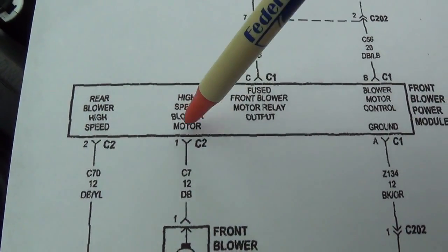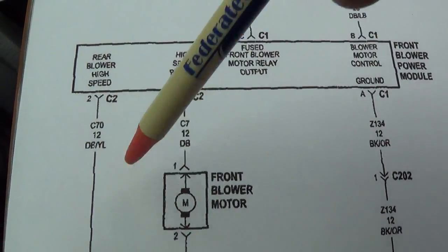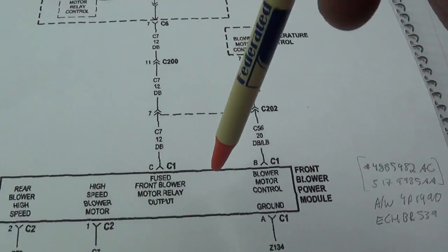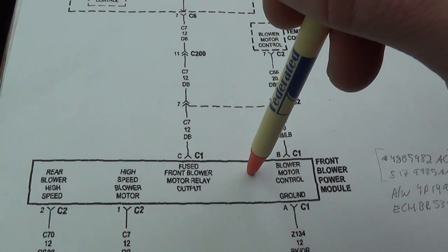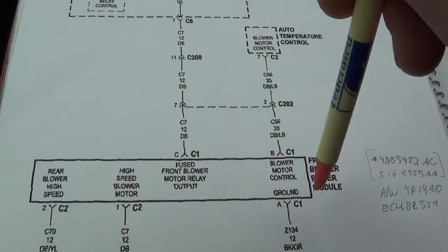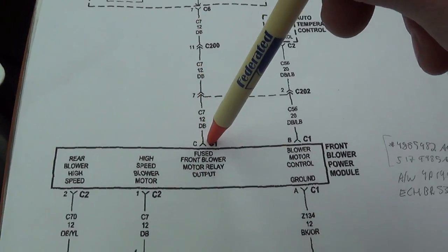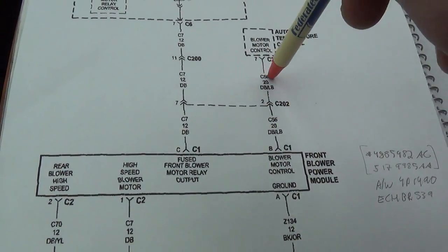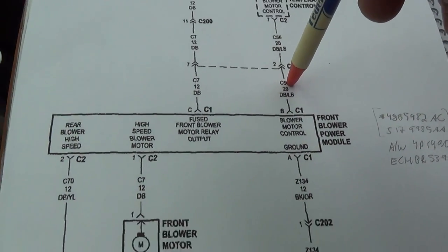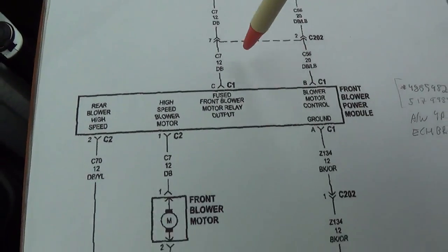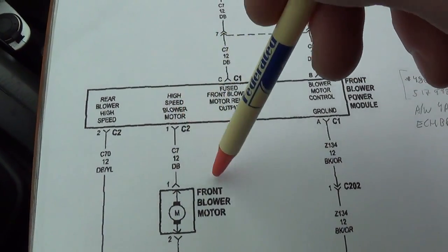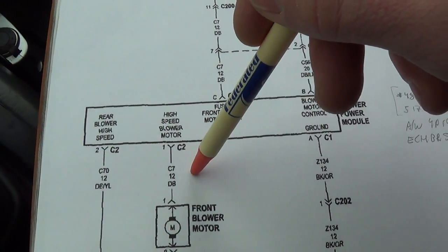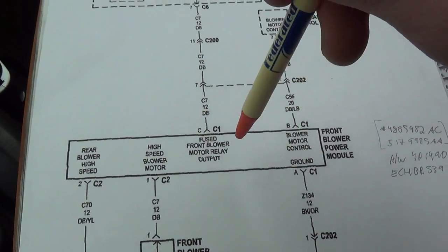This is all wrong, but all we're interested in is the wiring colors. Hopefully those are right. So this thing lives behind the glove box, so it should be easy to get to. And from here we can check everything. We can check the feed, ground, the pulse width modulated signal from our controller, and then obviously the front blower motor itself. We can even unplug it, send it direct power and ground, see if it works. So let's find this guy.